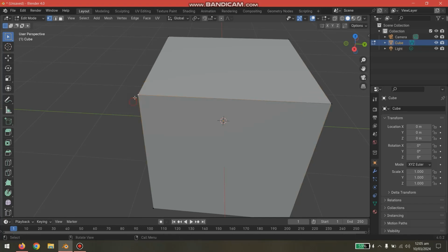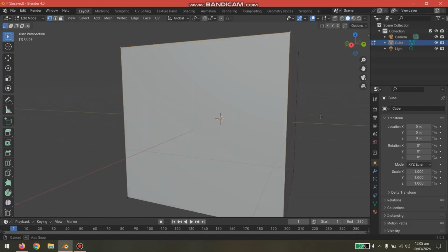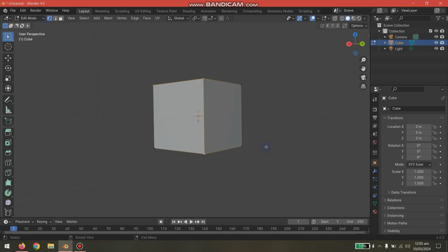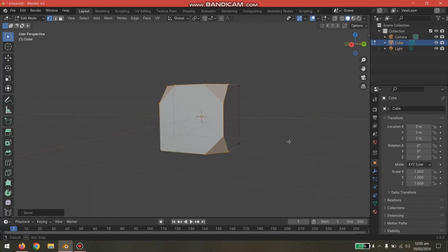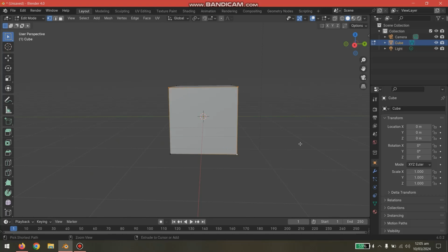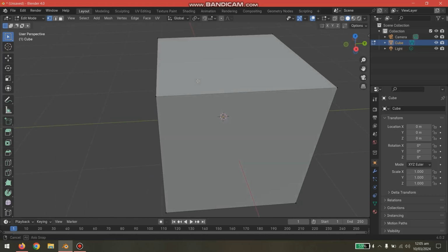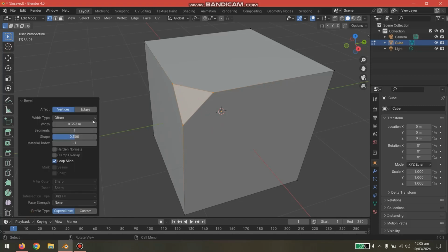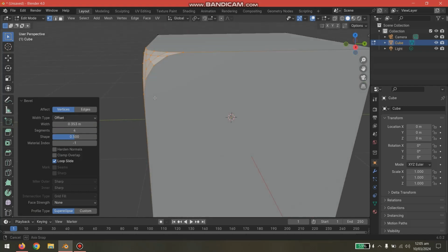The other thing I can do is select multiple vertices and just do this. Control Shift B, and I have cut it. And if I don't want to cut it in a very straight path, just Control Shift B, drag it, click it, and go to the bevel settings and select number of segments. So if I select some number of segments, it becomes a smooth cut. Okay, so I can maximum do 100 vertices, but kindly don't do that.